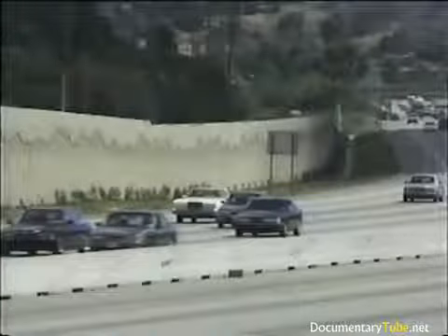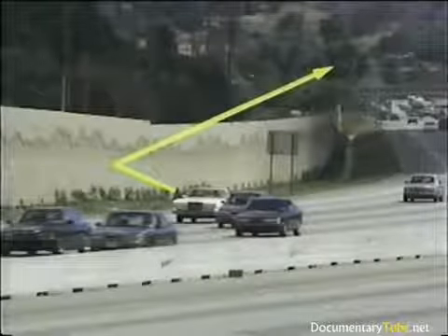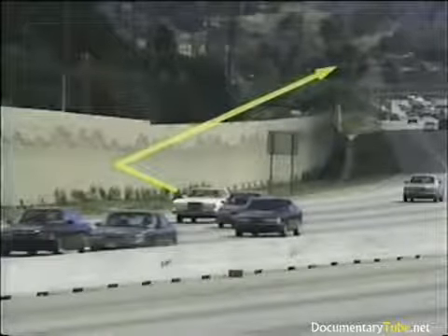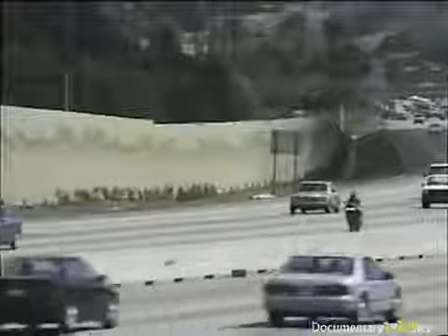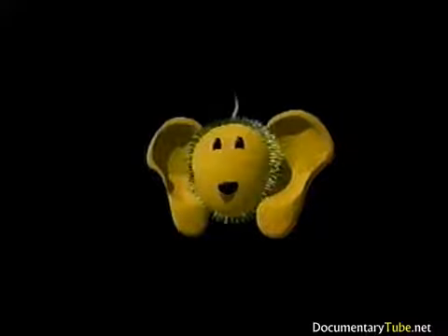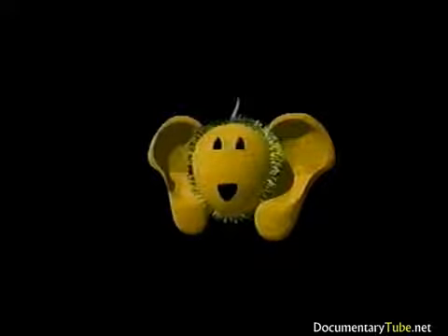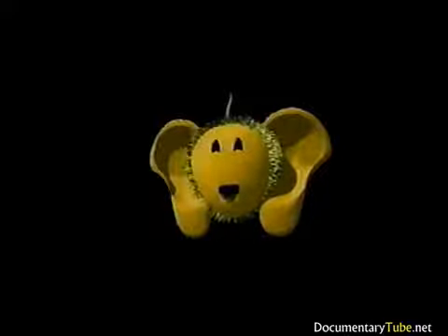A reflective barrier surface can cause noise to affect receivers on the opposite side of the highway. It is a common perception among such communities to hear a difference in the sound after the barrier is installed. Although theory indicates greater increases for a single reflection, practical highway measurements commonly show a 1 to 2 dB increase in sound pressure level from the no barrier case due to the sound reflected off the opposing barrier. Such increases can be considered typical for the first and second row residences. While this increase may not be readily perceptible, residents on the opposite side of the highway may perceive a change in the quality of the sound.